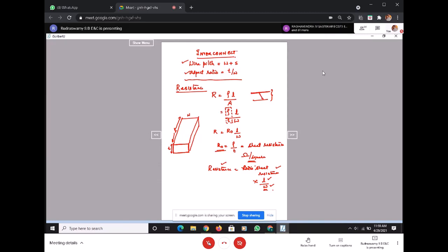That's one thing. As well, we can see there is a capacitance effect between any two wires. So the moment we have an interconnect, we have a delay in terms of the resistance and the capacitance, and we have crosstalk. These are the different aspects. The RC delay and the crosstalk are all matters of interconnect. So this is where we'll stop on interconnect.